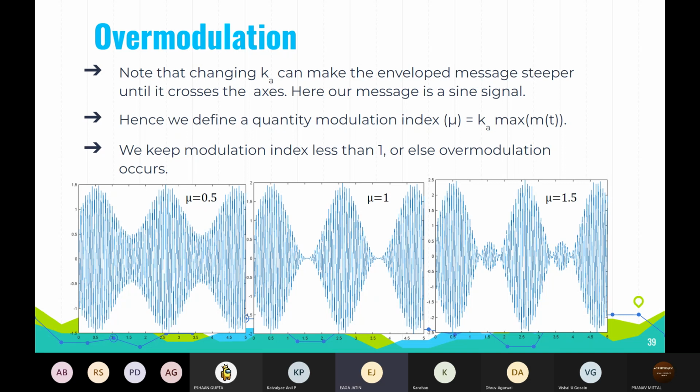As you can see in the third image, you start to see distortion in the middle of the waveform. That happens because of the over modulation. Although over modulation is sometimes considered permissible, it should not occur in practice; distorted waveform envelopes will result in distorted output, as you can see in the third image.